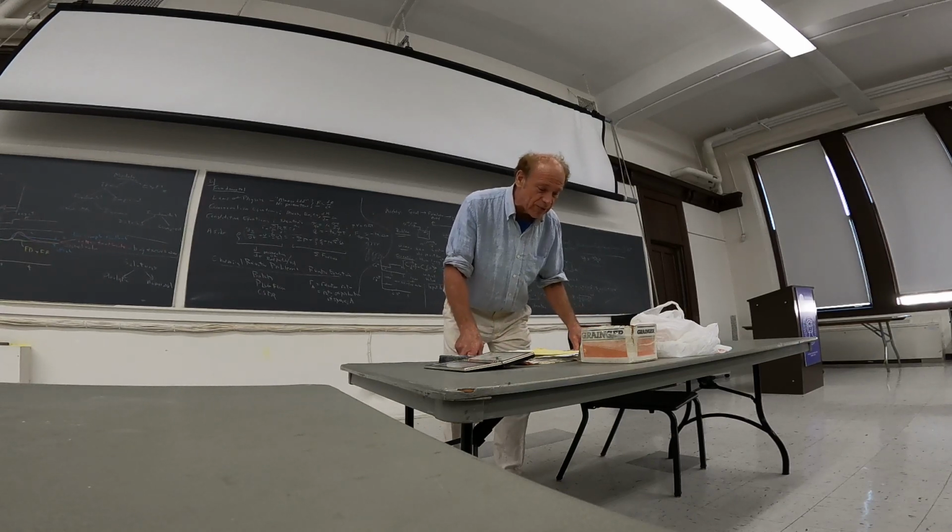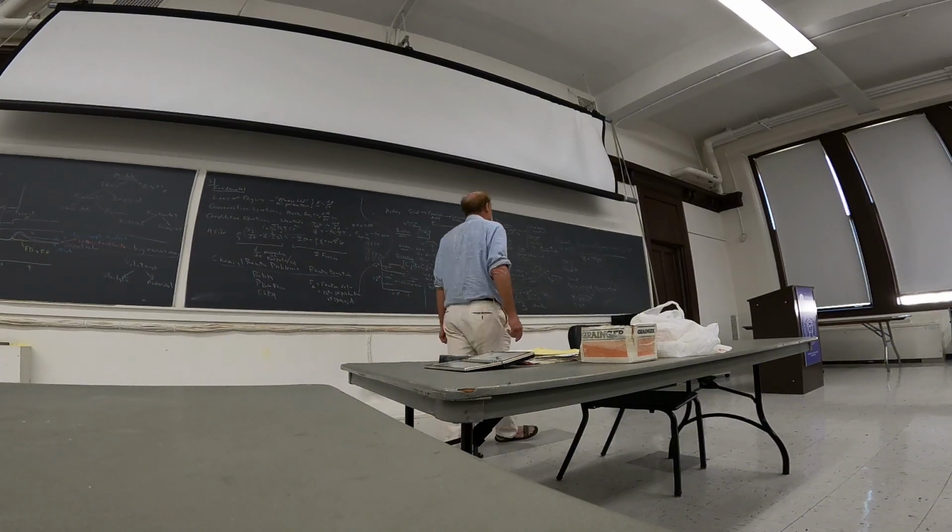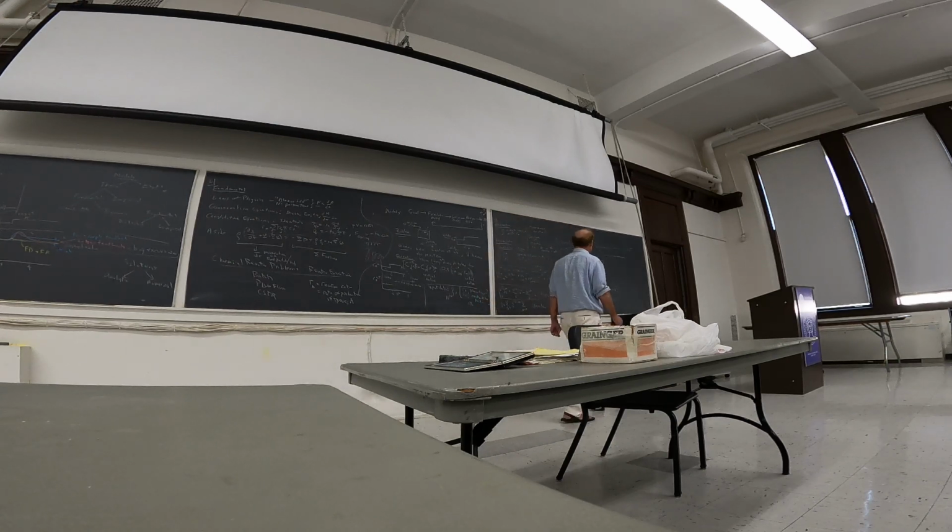Okay, so the next thing we have to do is the mathematical solution. Since I only have a couple of minutes left, I'm going to do a quick solution of the problem, but we'll analyze it next time. The reason I'm doing this now is I want to make the connection to ordinary differential equations. Let's rewrite this equation: dCA/dt plus CA over tau is equal to CA in over tau.